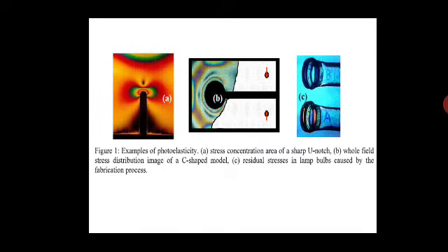If the plate is of uniform cross section, then whatever stress you are applying, we can directly consider the stress equation sigma is equal to F by A. But whenever there is a stress concentration problem, such as holes or voids in the module or in the structure, because of this kind of discontinuity the stress levels will vary. So in this condition, photoelasticity can be applied for such a member or a prototype member, and we can analyze the stresses and the deformation in the member.